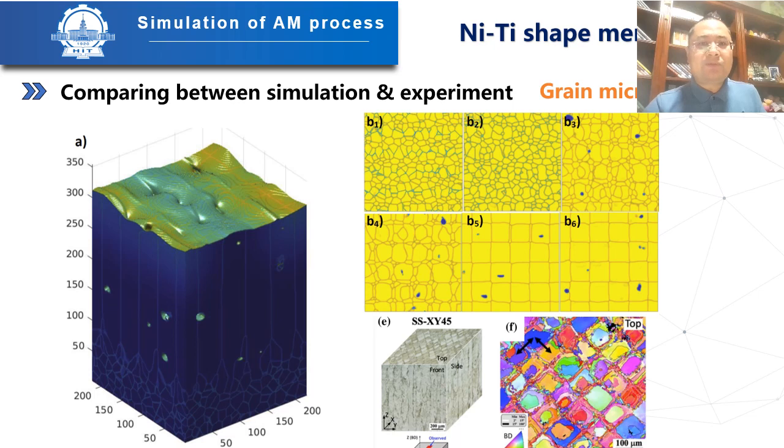This page features a comparison between the simulated grain structure and the experimental findings. Our simulation demonstrates that under conditions of low porosity, grains tend to form a well-aligned column structure with a grain size equal to the distance between adjacent laser tracks, which is the hatching distance. This simulation outcome is notably consistent with experimental observations.